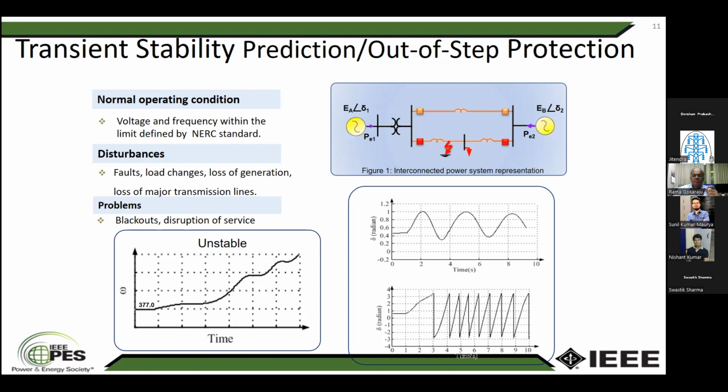per unit. But for an out-of-step condition, they are 180 degrees separated. So it is going to be 2 to 2.5 times. So for a 400 kV system, it is going to be an RMS of about 800 kilovolts minimum. Having a circuit breaker for that large a rating is going to be very expensive. So that's why we wait for a favorable angle.